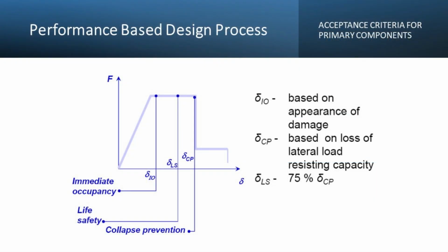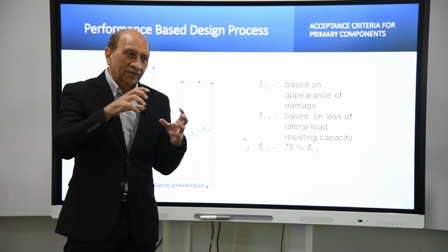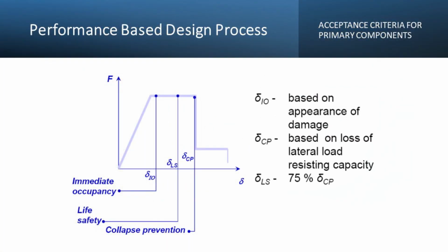And then these are the curves that have been developed, which basically bring it back to what I showed you in the slide, where we have the material definition, which is the stress strain curve. So we can have the stress strain curve, a moment curvature curve, a load deformation curve, and on those curves, we can put the lines which correspond to the same performance levels that we have for the structure. Immediate occupancy, collapse prevention, and so on. So everything is completely on the same scale, right from the structure to a particular cross-section or even a material.